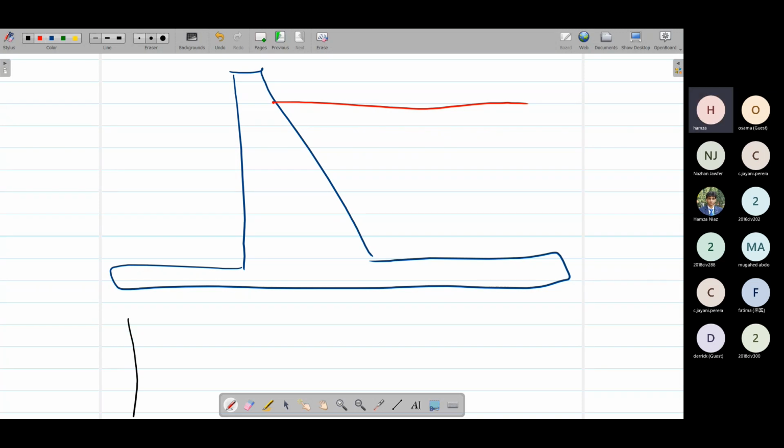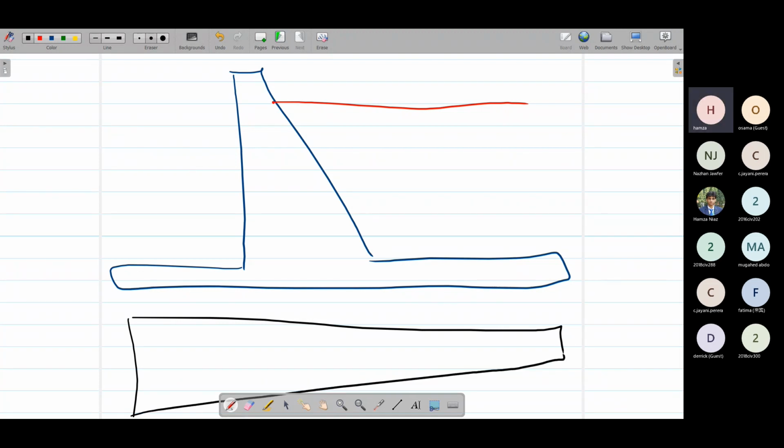It would be something like this, trapezoidal. We are going to name this coordinate y1 and this one y2. If you remember, we use the same concept in the second case of base load also in the steel portion. So our y1 should be P over A, force over area, plus My over I. Similarly, y2 would be P over A minus My over I.